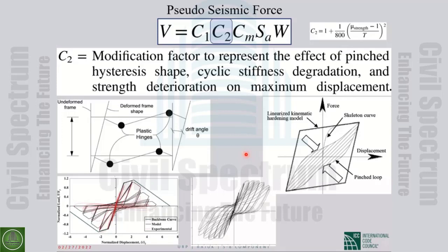One very important aspect for existing buildings is the shape of the hysteresis curves. Usually when a new seismic system is being designed or invented, the inventor tries to show that the system has very stable hysteresis loops. The seismic system should get damaged in specific points, for example, in moment-resisting frames, in the beams.